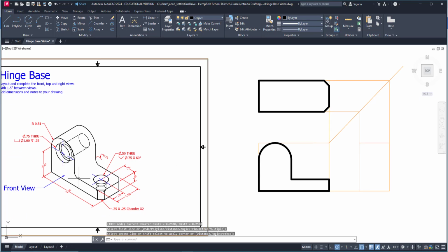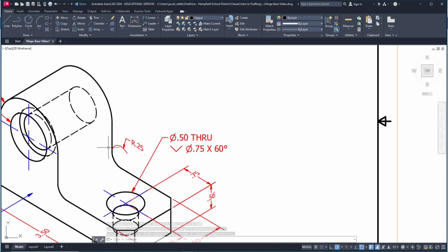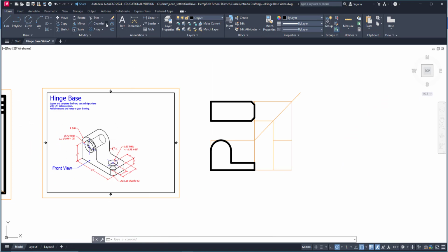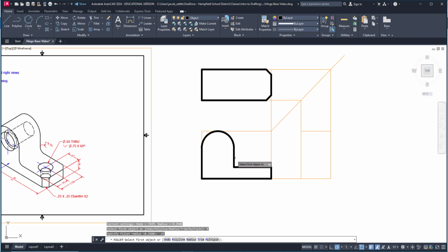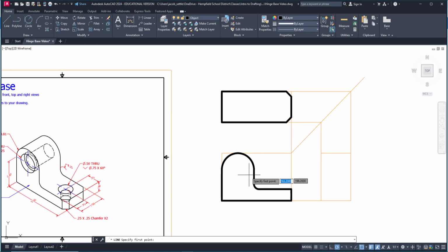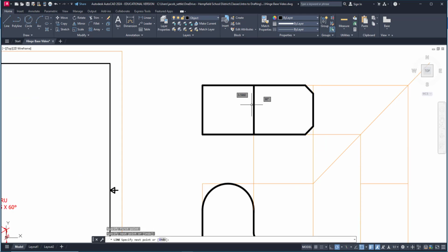While we're doing some edge treatments, I'll also do the fillet here. This fillet is 1/4 inch, so I'll go back to my fillet tool and select the radius button and type in 0.25, and then I can go in and add that fillet in. I will have an object line from this edge here, so I can object track that up, or you could switch over to your no print layer and you could draw a line up to this point and then switch back to object if that's easier for you. Either way would be fine.